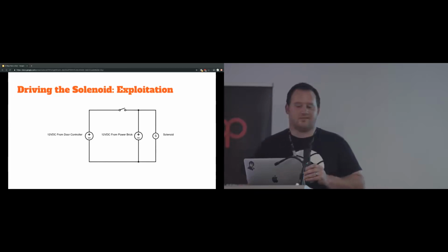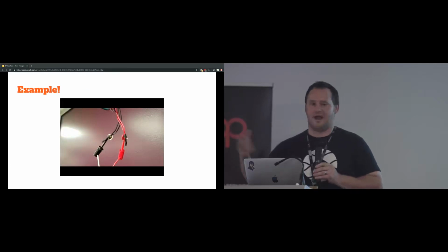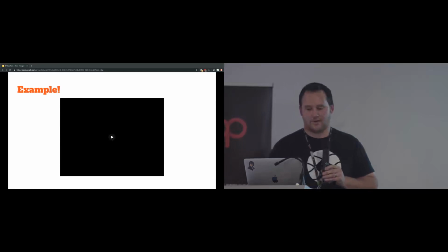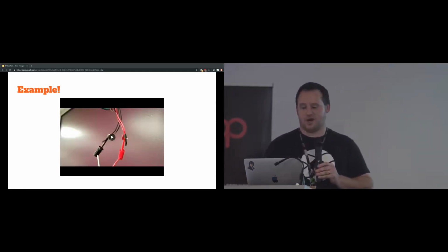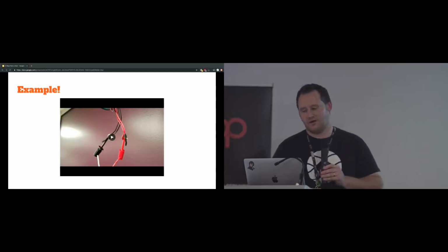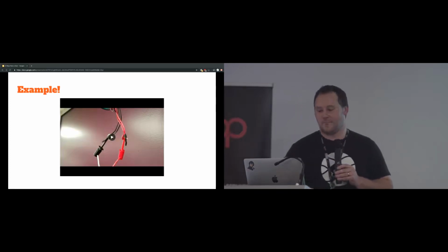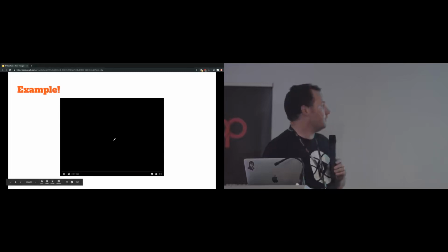So what if we get access to the door wiring, maybe in the tiled ceiling directly above the door, and we provide the solenoid with our own 12 volt power source, for example from a power brick or a little battery pack? Okay, so what we've done here is we've had a rummage around in the ceiling by the door, and we found a junction box containing a bunch of door wiring. Opening the junction box exposed a whole bunch of joins, and I've gone super high tech and just jammed a drawing pin through a couple of these. I've then connected this to a 12 volt power source with some interesting results.